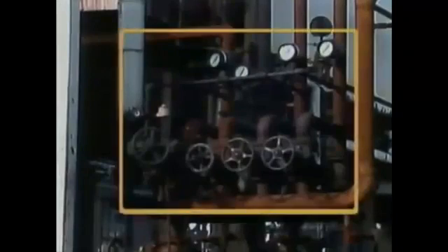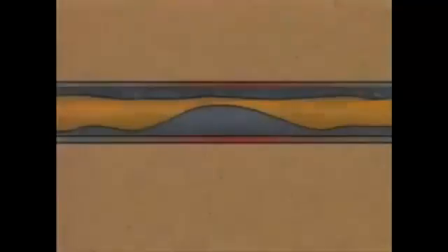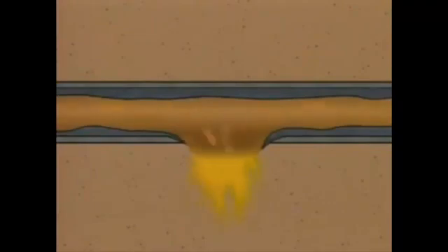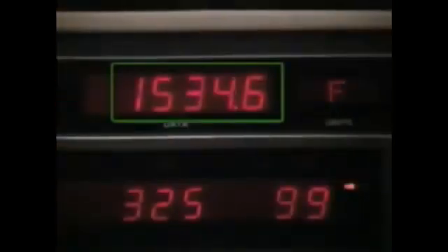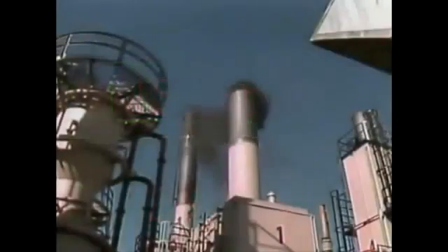This system injects steam and air through the tubes to remove the coke deposits and carry them out of the tubes. Another tube problem is a tube leak. When a tube ruptures, any flammable process fluid that escapes is likely to catch fire in the furnace. A high stack temperature is one sign of burning process fluid. Smoke coming from the stack is another.